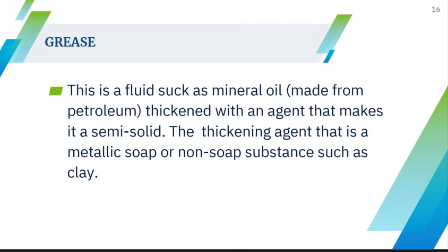Good grease must have consistency, stability, oxidation resistance, ability to protect against friction, wear and corrosion, and feedability. This is the ability to flow through dispensing equipment such as wheel bearing, universal joint, ball joint, and chassis fittings.